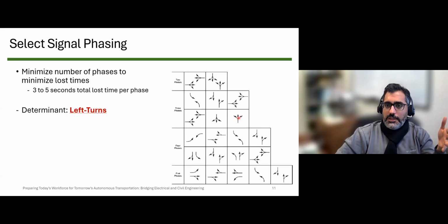Everyone else should stay behind them. So in that case, we will split them from each other to give opportunity to everyone to move in one direction. Another example would be if the intersection is too tight, too narrow, that the two left turns, if they happen at the same time, they will collide. That would be another reason for this split phasing example.